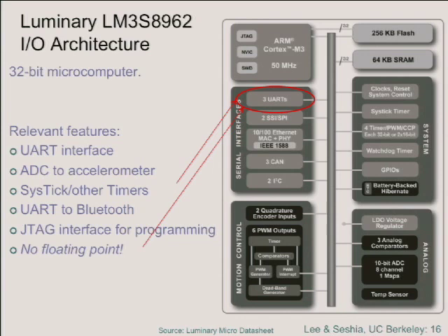Actually, the speculation is that the programming is easier for the serial interfaces, but it's the reverse. Programming is easier for the parallel interfaces because if you have, say, a 32-bit architecture, and you have 32 wires, you just write to them a word. Bang, out it goes. If it's a serial port, you've got to figure out, are you going to send the low order bit out first or the high order bit? What if you get it backwards? How do you shift out the bits? So it's actually a little bit harder with the serial interface. The software is a little bit harder.